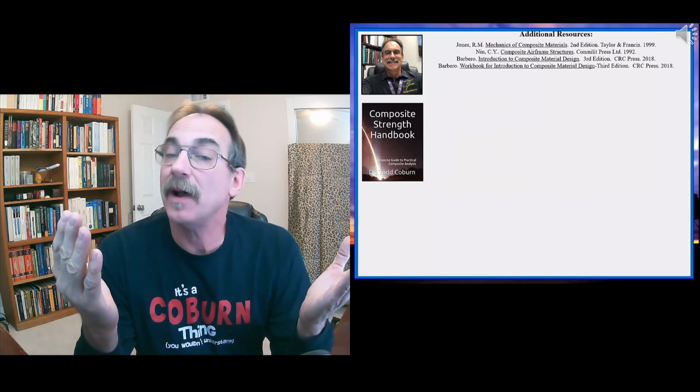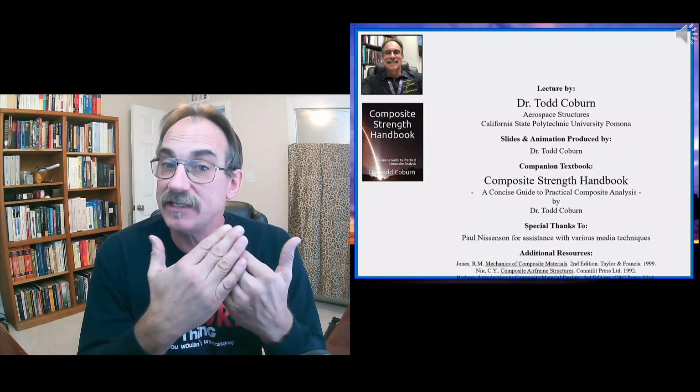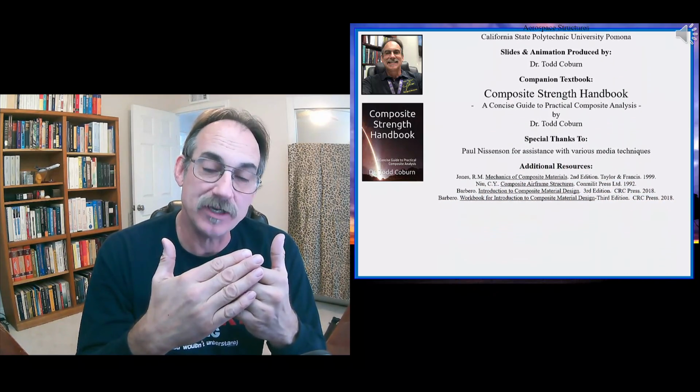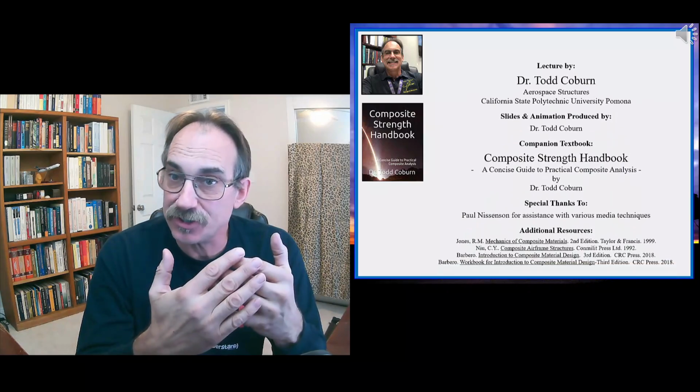Now remember, temperature induces strain but not stress unless there's a constraint. And pretty much by definition, when we have a composite made of multiple materials or stiffnesses that are different in different directions, any attempt to strain is going to introduce stresses between the different parts of the laminate. And same thing with moisture, which is going to induce strains in a manner that's analogous to temperature. That's going to introduce stresses when each lamina tries to strain in a different manner and it's resisted by the other elements of the laminate. So stay tuned, practice this, enjoy.